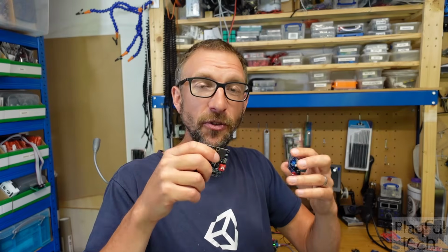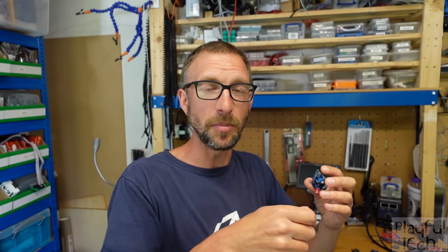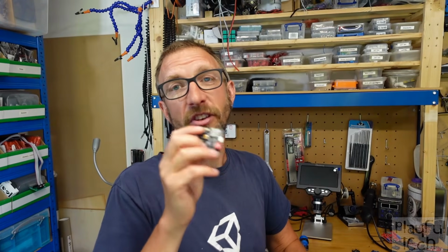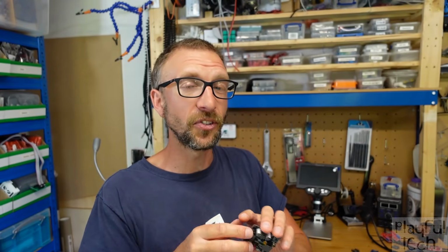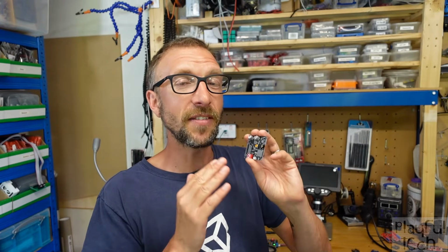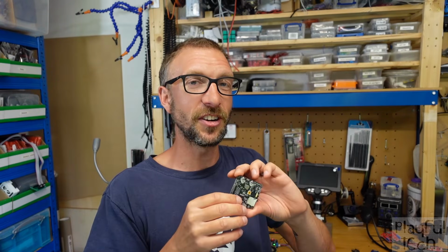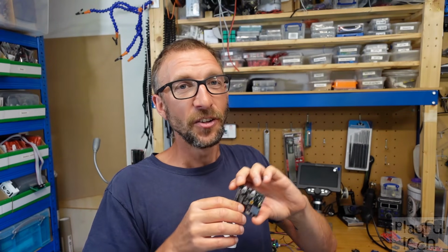And the difference compared to the previous family boards is that instead of being powered at 5 volts, you power them with a DC input between 6 volts and 35 volts. And in return, instead of having a 5-watt amplifier on board, you get a 20-watt Class D amplifier. So that's equivalent to what you might get from an electric guitar amplifier, for example.